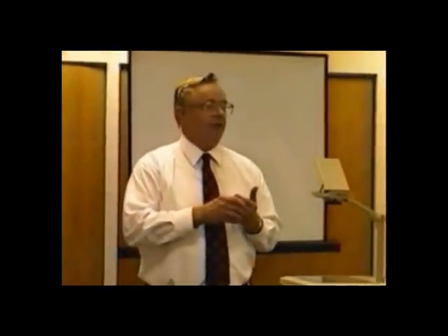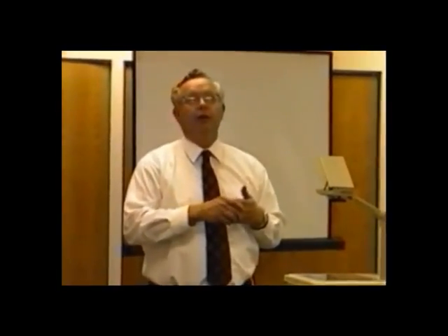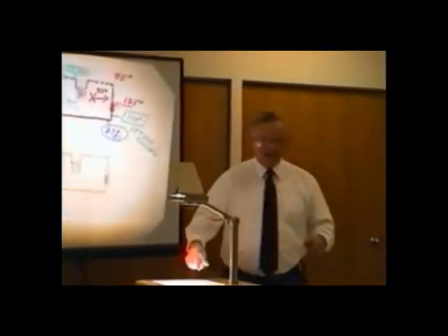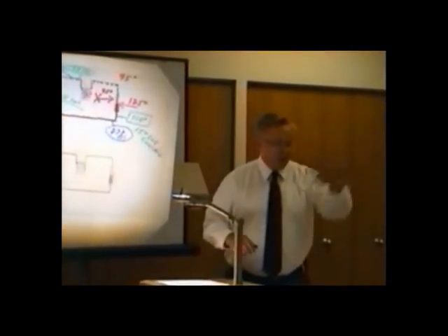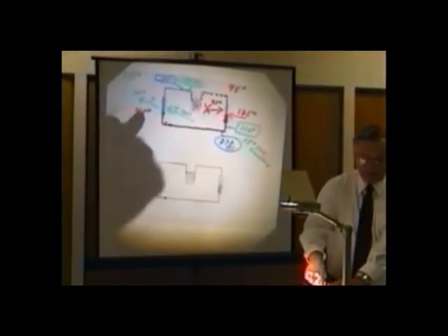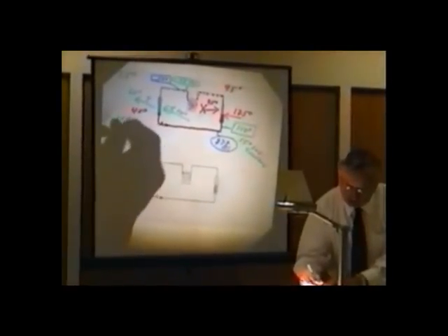What is the definition of superheat again? I've got to try to remember that one. Definition of superheat is something like it's warmer than the change of state temperature. That would be a method. Definition of subcooling, it would be below the condensation temperature, which is still the saturated temperature. So again, there are different ways of talking about definitions. But definitions mean nothing if you don't know what they mean. So you understand, gentlemen, under these conditions, this suction line is how many degrees warmer than my evaporator? 10. So I have 10 degrees of superheat.